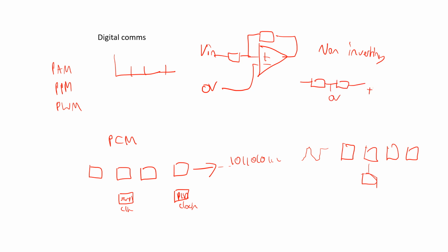That will be positive or negative voltage. And then we'd work that one out just by doing voltages across there, voltages across there. It's basic potential dividers or ratios, isn't it? If they were the other way round, you'd have 0 volts on the left-hand side, and again you'd just use potential dividers.